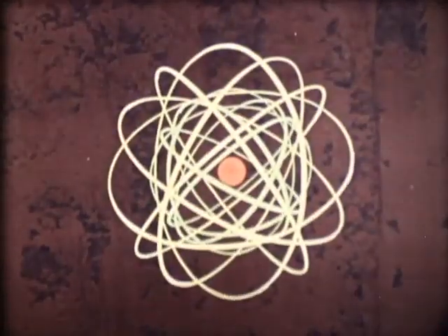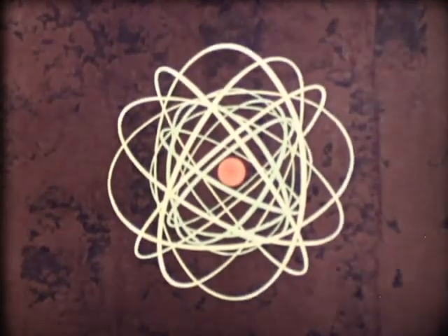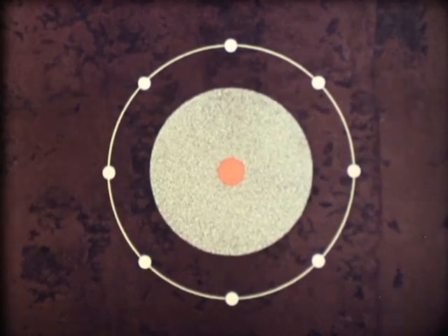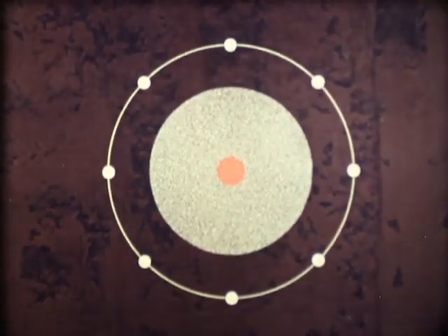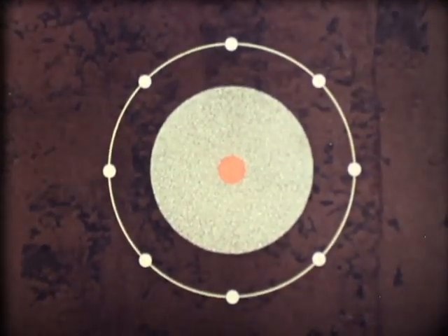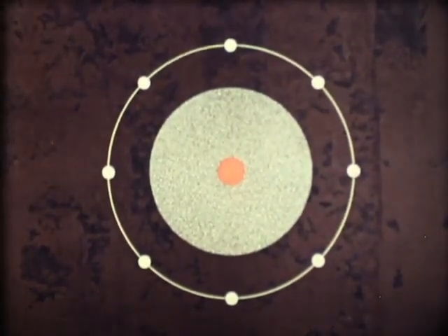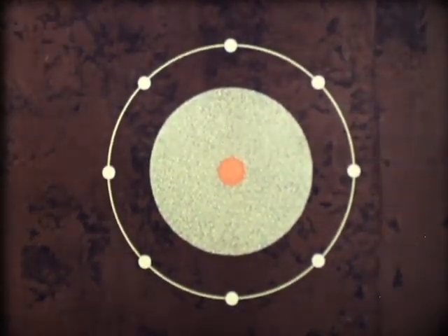The photoconductivity is due to the electrons in the outer shell. These electrons are exposed to two forces. Firstly, the attraction of the positive nucleus, which binds the electrons to the atom, and secondly, the force exerted by the electric charge of the signal plate.